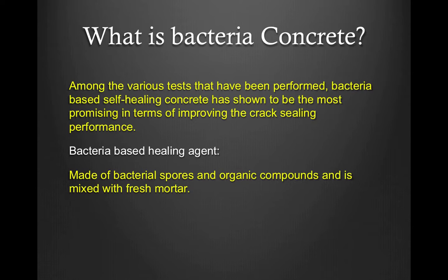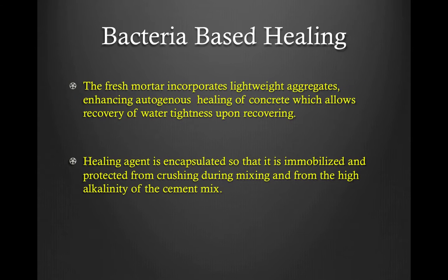Among the various tests that have been performed, bacteria based self healing concrete has shown to be the most promising. The healing agent is made of bacterial spores and organic compounds and is mixed with fresh mortar. Bacteria based healing. The healing agent is encapsulated so that it is immobilized and protected from crushing during mixing and from the high alkalinity of the cement mix.